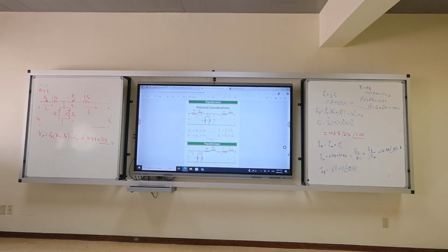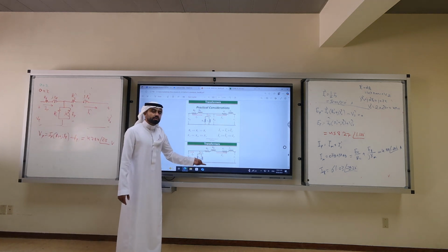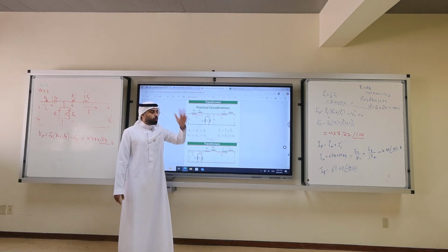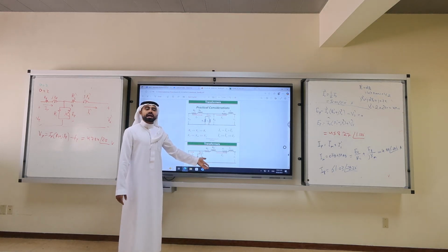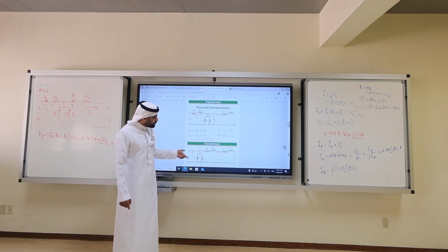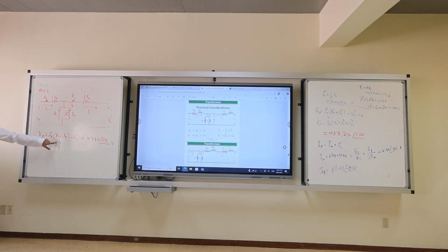It depends, but you can survive it. What benefit do I get here? We did 2 KVL and 1 KCL. With this, you get a discount of 1 KVL, because you end up doing EP equal VP, so that KVL is not used. You get 1 discount.